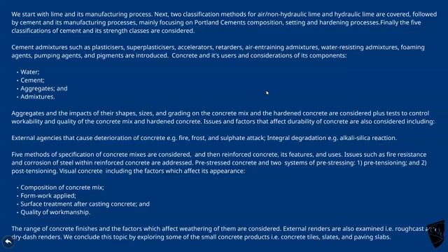We'll look at things that can adversely affect or cause the concrete to deteriorate, so you know, fire, sulfate attack, that sort of thing, especially alkali-silica reaction, otherwise known as concrete cancer. There's 5 methods of specifying concrete mixes, which are mostly covered in the essential readings, to be honest with you in this. And we'll look at reinforced and pre-stressed concrete.